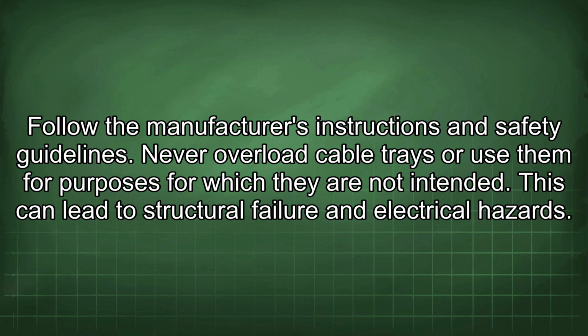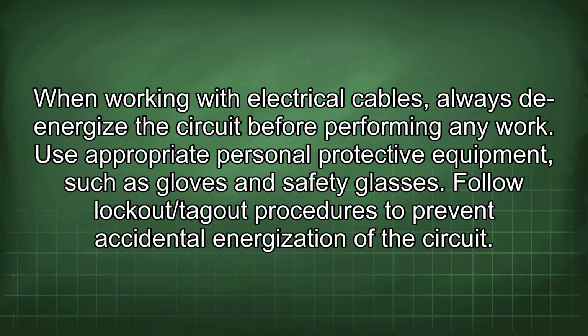Never overload cable trays or use them for purposes for which they are not intended. This can lead to structural failure and electrical hazards. When working with electrical cables, always de-energize the circuit before performing any work. Use appropriate personal protective equipment, such as gloves and safety glasses. Follow lockout/tagout procedures to prevent accidental energization of the circuit.